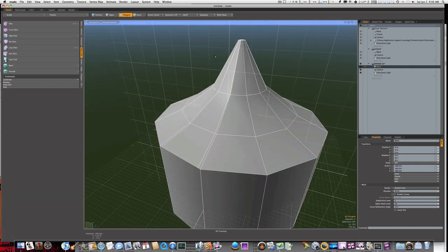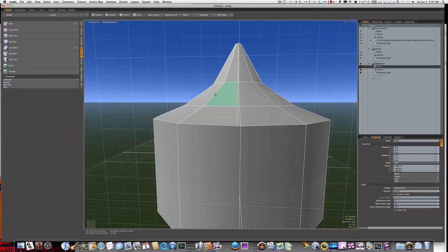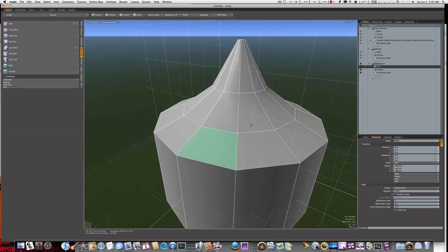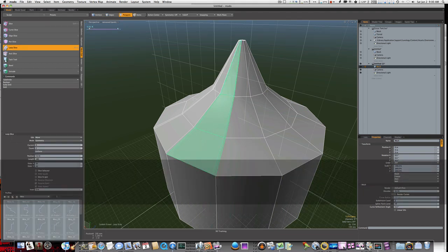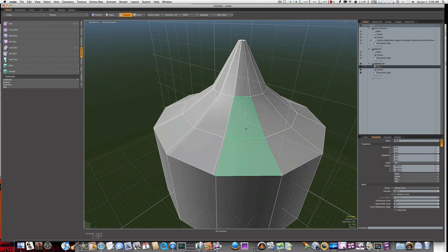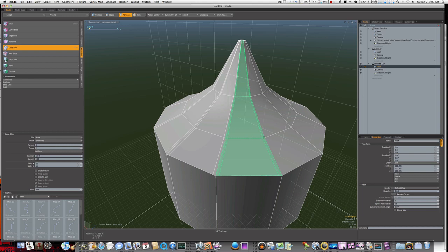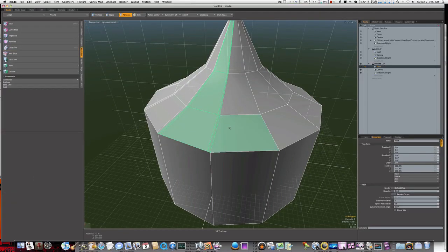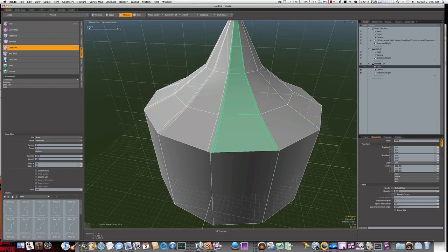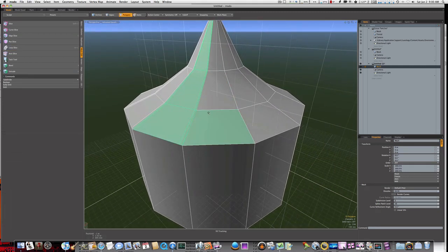Now you can see that run 2 loop slices right down through there, but it did not run them down here because these are 2 separate items. So let's go around and run loop slices all the way around on every section. Okay? So it's easy. As you see, I just select 2 in the direction I want to run the loop slice, hit Alt-C and click. It's already set to 5% because I had the tool set up from last time I used the tool.